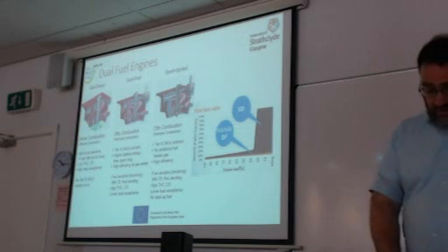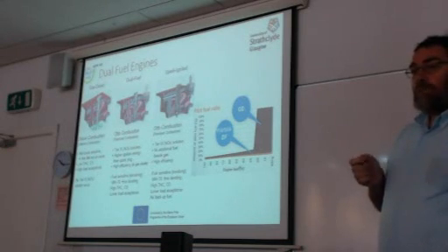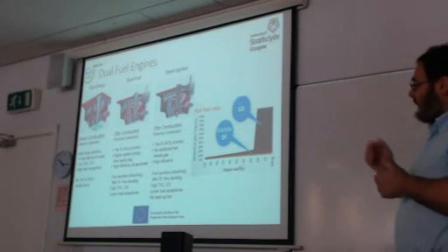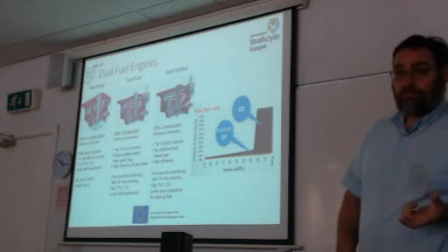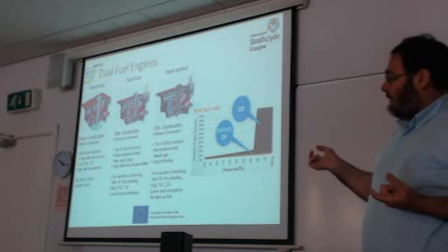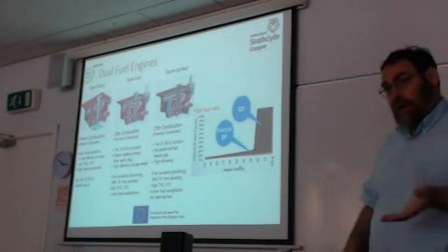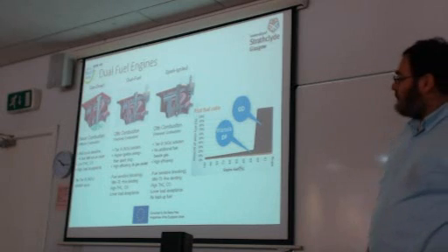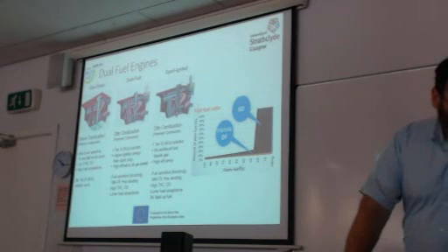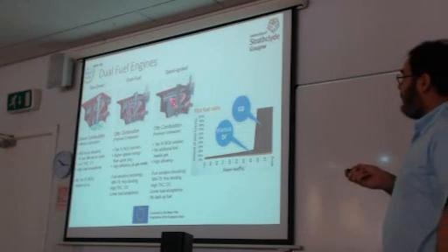So it needs a methane number above 70. It is knock sensitive, which means that it can operate in a lambda window, where the lambda value should be from 1.8, 1.9 to 2.2, usually in this region, as I will explain later. And the unburned hydrocarbons and CO are high. Why? Because, as I mentioned in the previous category, as the pressure is high, hydrocarbons are low, but in this case the combustion pressure is lower, so that increases unburned hydrocarbons and carbon monoxide in this type of engine.